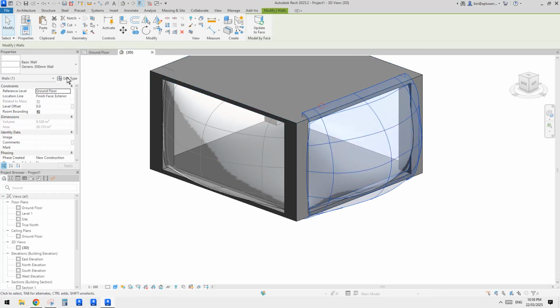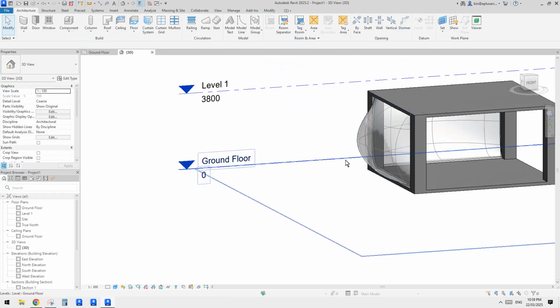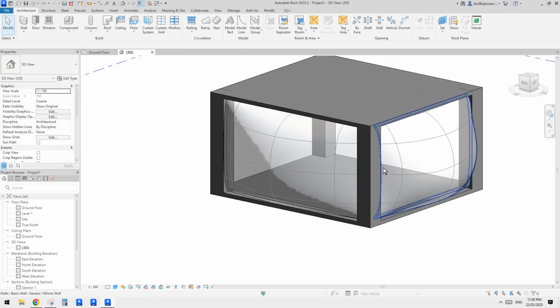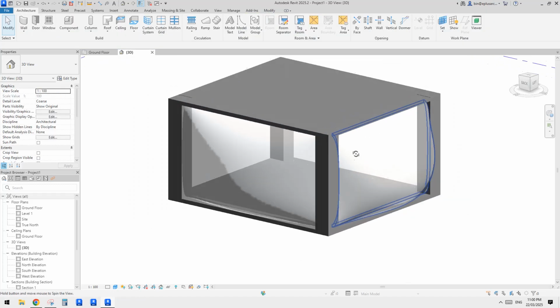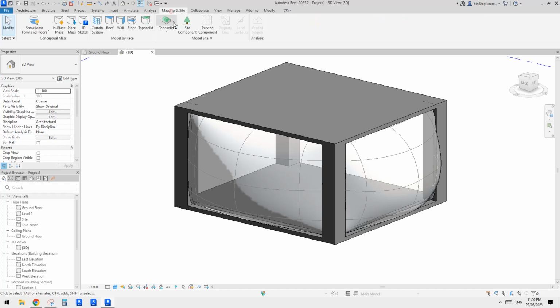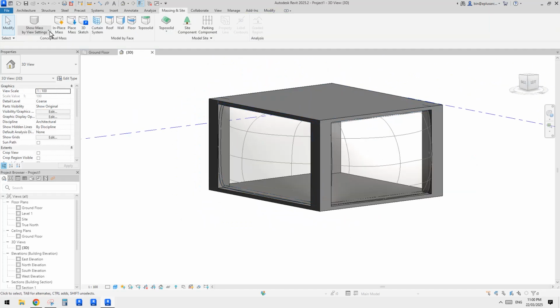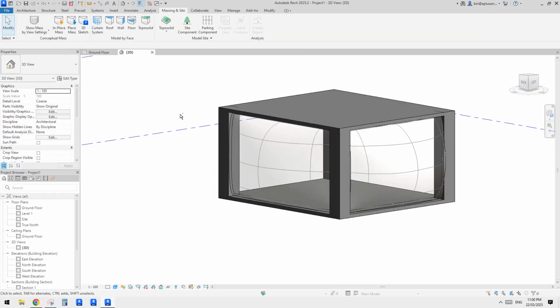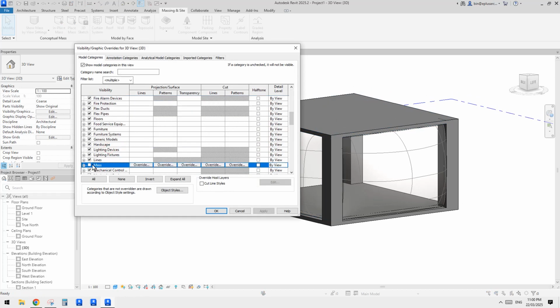Okay, looks like we still have the issue, let's change it to 100 wall. So maybe we try to flip it. Okay, so that's it. And finally, once you have the wall, you can turn off the massing. You can actually go to massing and click on this, so it will hide the mass. If it's still visible, just double check, go to VV to make sure this mass is unticked. If it's ticked, it will still be visible.